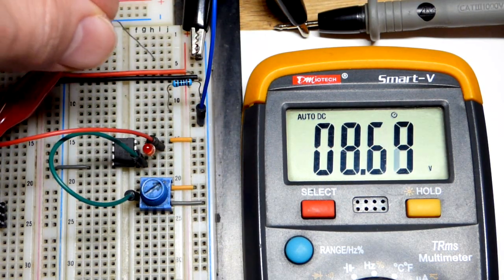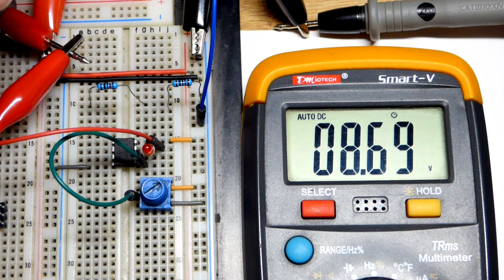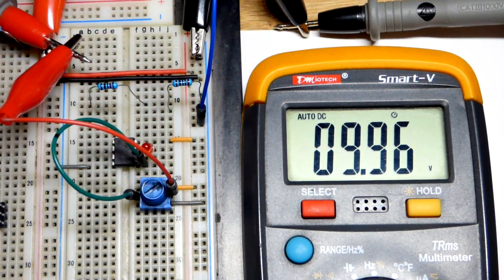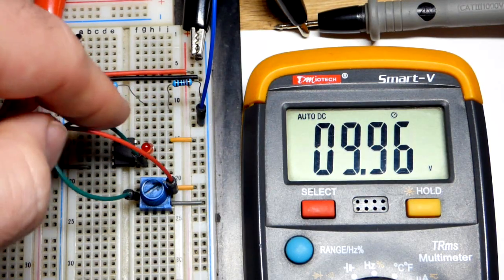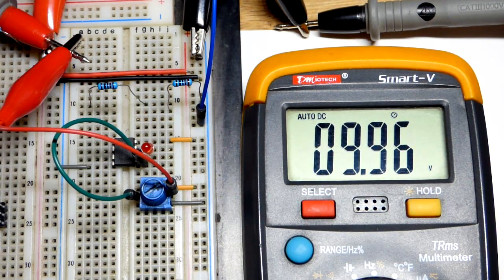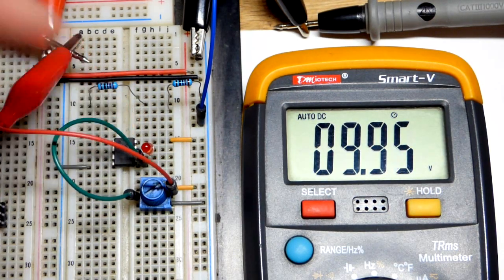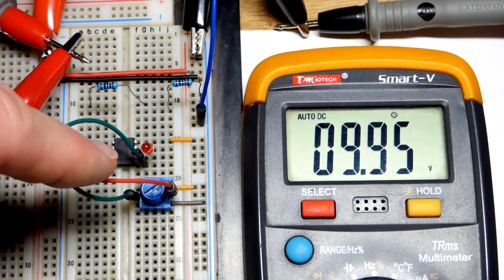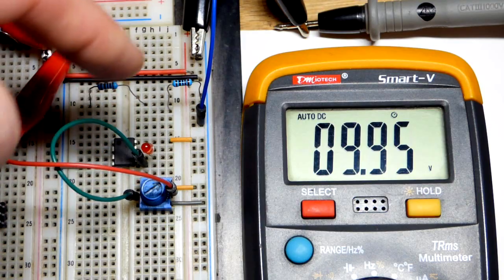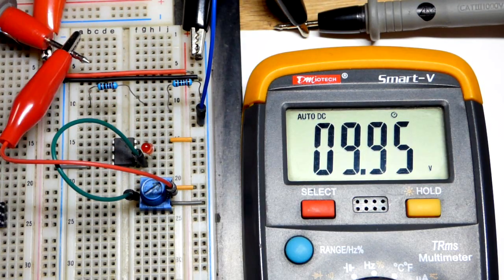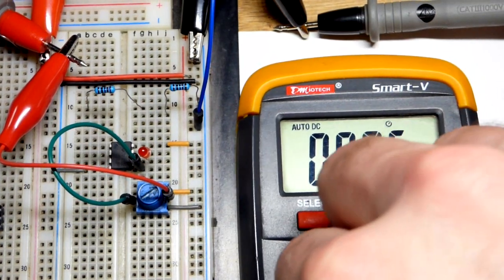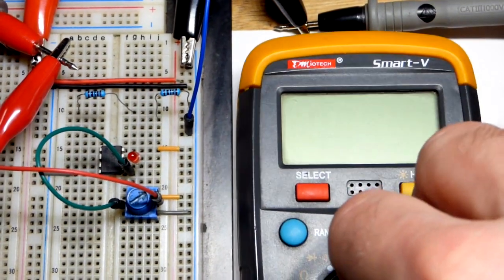But even with no load, not having to provide current, it's not giving us that full 10 volts of the supply. That's something you always got to be aware of with the outputs. They have limitations. And again, even without a load, this doesn't go to the positive supply. Some can go all the way to the positive supply and the negative supply, but not when they have to deliver current. They might fall like a volt short or something. So you always got to learn the limitations of the output and work within those limitations.